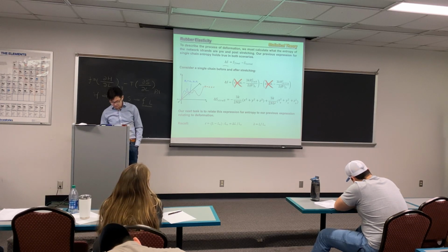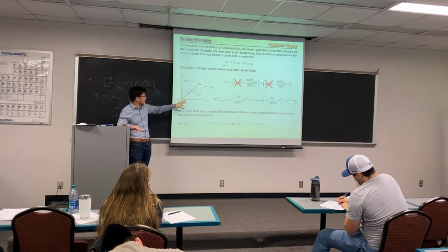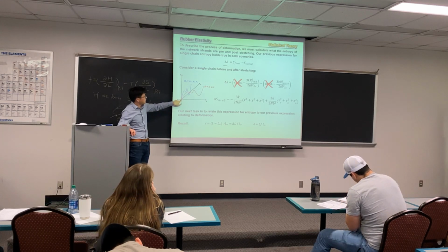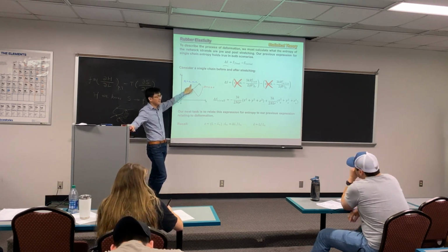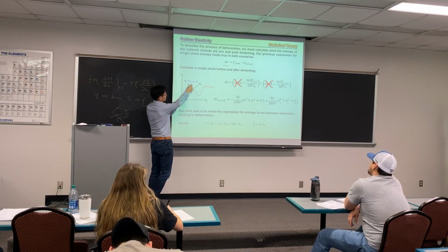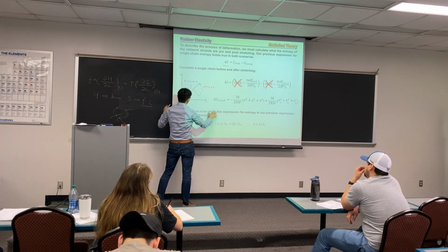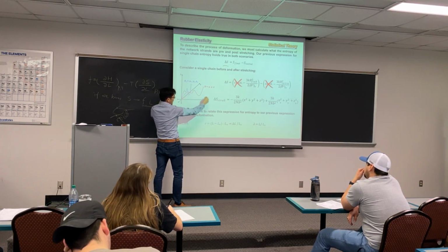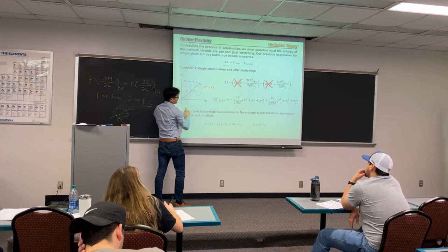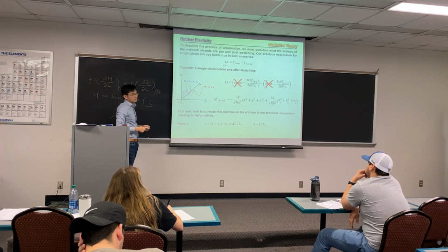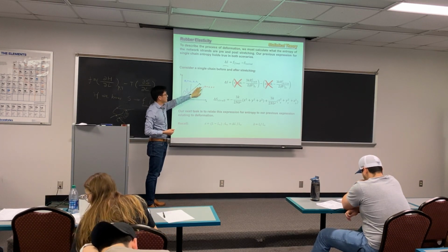And we just need to give a scenario. So on the figure shown here, look at this curve. Imagine this is a polymer strand. It starts from the origin and goes out to the chain end here. And this would be your initial end-to-end distance R0 inside a rubber band. So imagine there's a rubber band, and these are between two cross-link points. If I pull the rubber band this way, this point will start to deform to there. And we can calculate the entropy of this strand before we deform it and after we deform it.